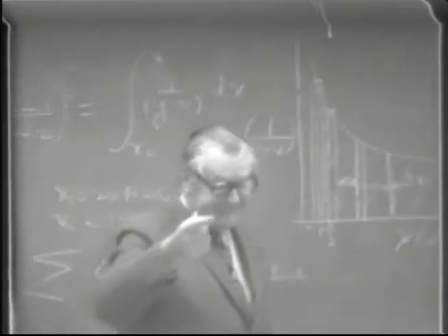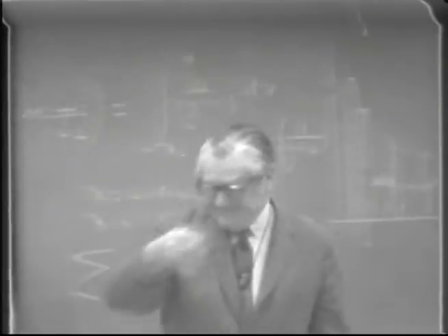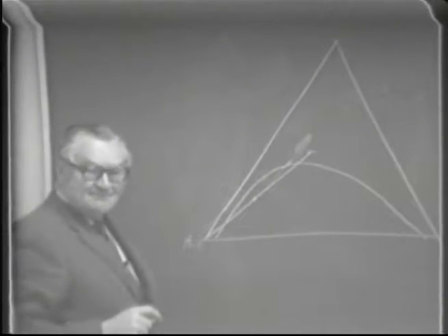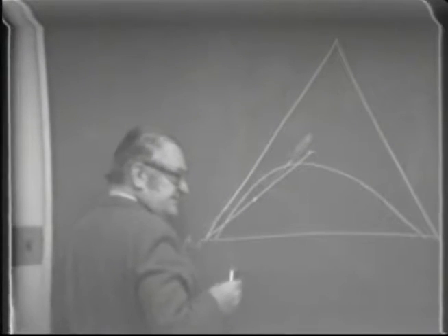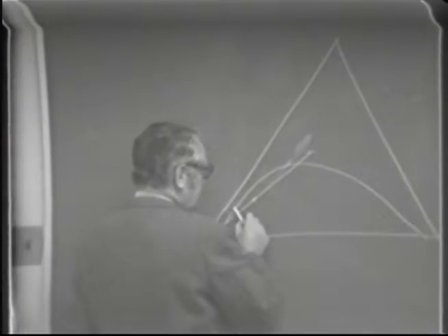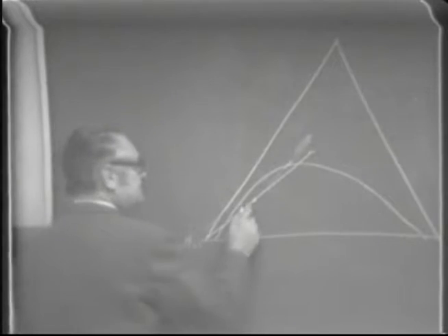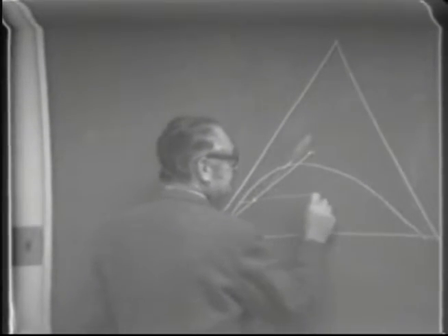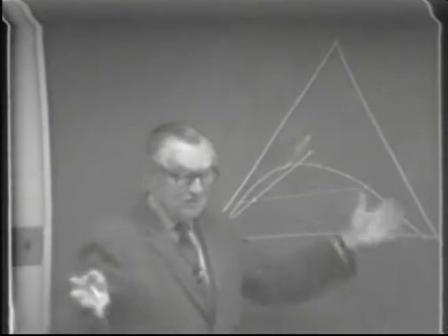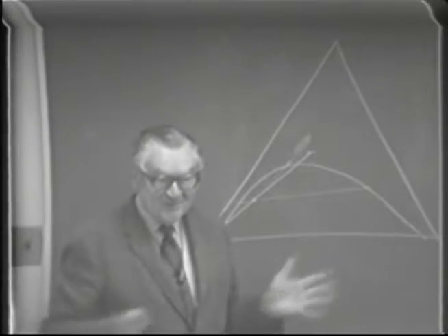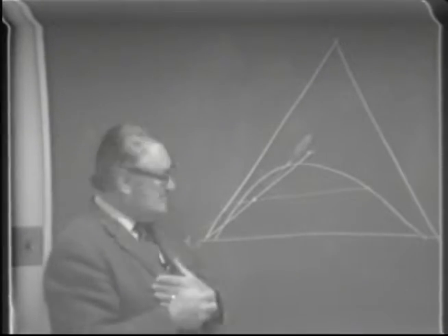And after we have added the amount of water that is stated here, you will end up somewhere down here on this line. And it probably doesn't coincide with one of the tie lines that are drawn on the graph, but if it isn't, you draw one in there by estimation. These are not quite parallel, but by eye you can draw it in a reasonable, proper curve from looking at the others.